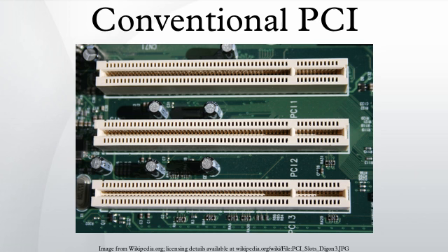Cards and motherboards that do not support 66 MHz operation also ground this pin. If all participants support 66 MHz operation, a pull-up resistor on the motherboard raises the signal high and 66 MHz operation is enabled. At least one of PRSNT1 and PRSNT2 must be grounded by the card. The combination chosen indicates the total power requirements of the card.